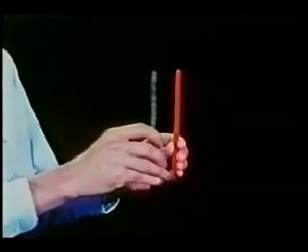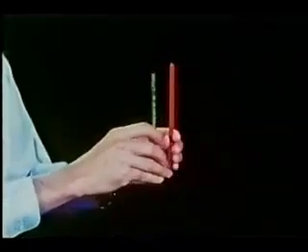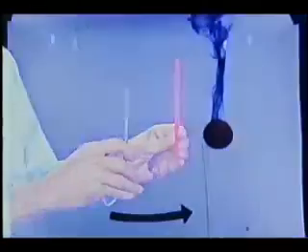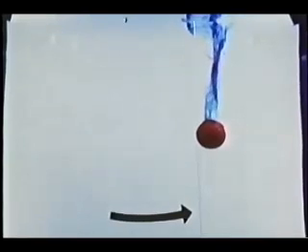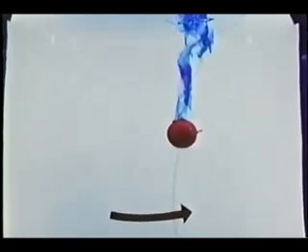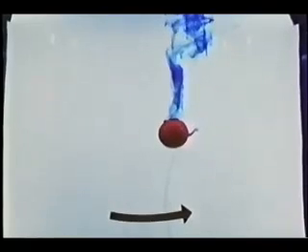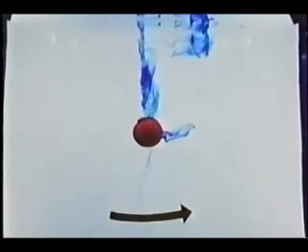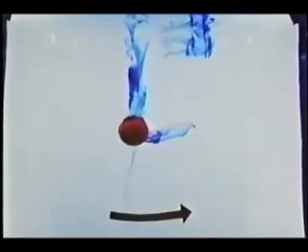Towing the sphere again, at low Rossby number and low frequency ratio, the two-dimensional Taylor column appears. We increase the towing speed. At this high Rossby number, the motion becomes three-dimensional and the Taylor column is left behind. Here's the same motion seen from above. When the ball is accelerated, it swerves to the right, like the earlier vortex ring.